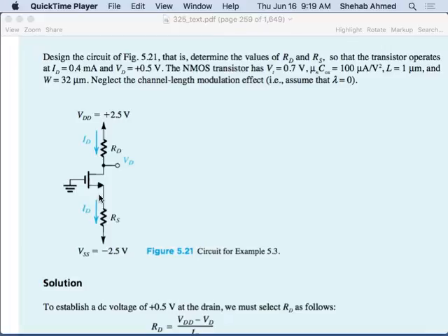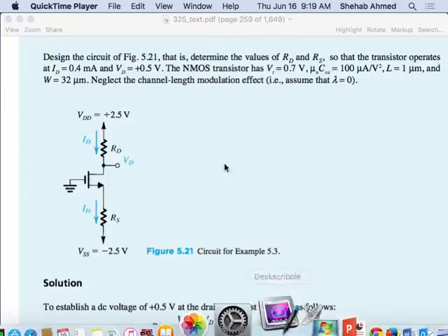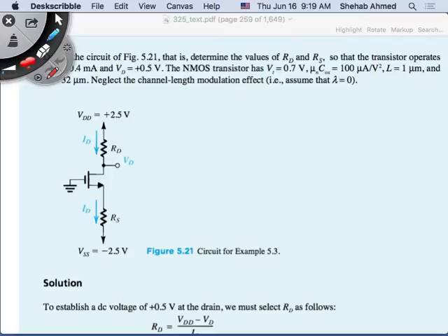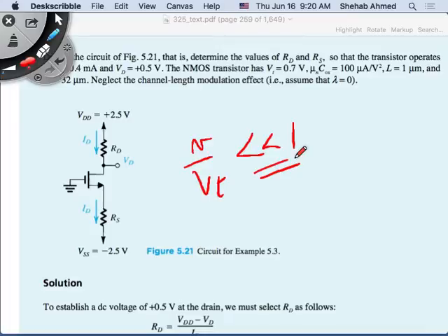Now we would like to see how we deal with our small signal. What value of small signal can we add? Remember in the diode, what did we do? We had a limit. Our limit was 5 millivolts across the diode. That came from a physical constraint. In our diode case, the voltage of the diode over VT has to be smaller than 1. We will have another condition here, which our small signal has to satisfy.